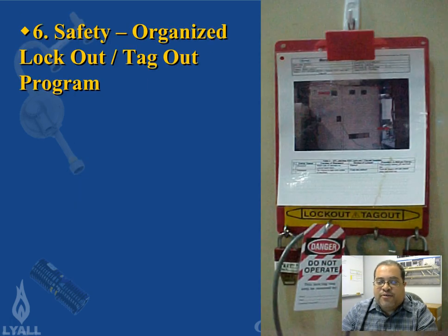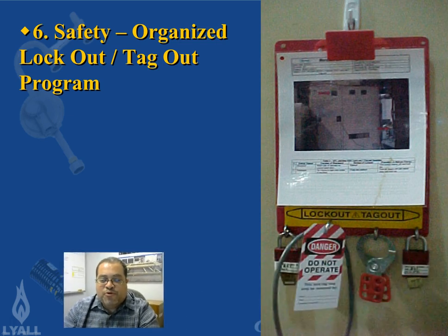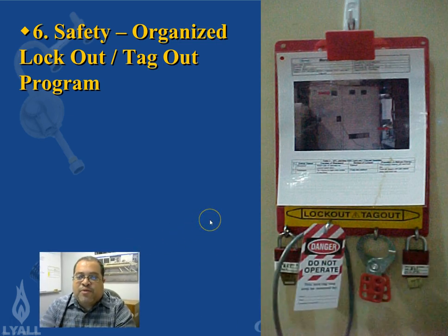Okay, lockout tagout is a very, very important thing in most industrial environments. And what is that? It's actually a lot simpler than it seems at first. You have some instructions, but the basic concept is this. You have a set of locks. Anybody in the organization who works with the equipment or has the minimal amount of knowledge is authorized to lock out a machine if there's a dangerous condition. But only a trained and skilled maintenance person or engineer is allowed to remove the tag when the safety issue has been resolved. So what's the idea of this?